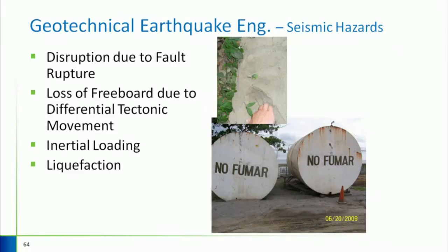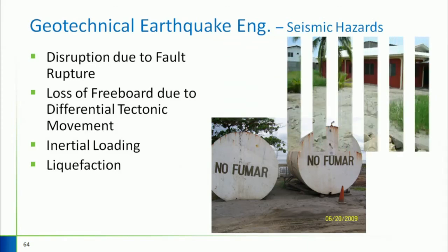Not necessarily a bad thing, except sand works on friction, which is a function of how much pressure it has on each particle. So if the water is pushing these apart from each other, they're getting less strength because they have less friction. And until that water pressure dissipates, you are going to have a very low strength material. But it causes sand boils, it causes tanks to sink and rise. It'll take over buildings that were once all grass. This is all from Honduras, by the way.